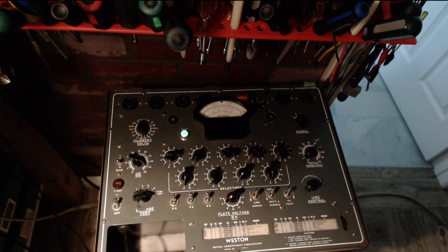So I'm going to think about that 6V6 replacement idea. It has to do with a big variation in the grid biasing. Grid biasing on the 6F6 is like 22 volts, and on the 6V6 it's half that. So if you over-bias the tube, you drive it into cutoff or get distortions or who knows. It looks like it's something you could try and see how it works out. I'm going to ponder that. 6V6s.